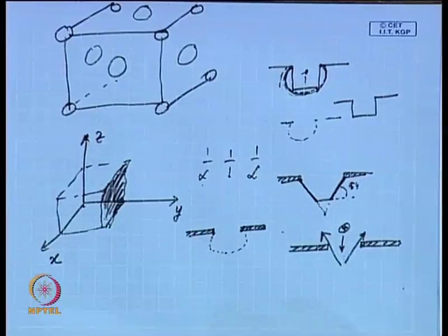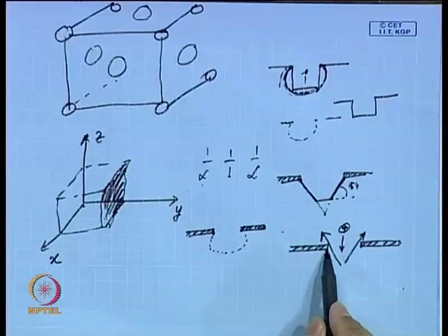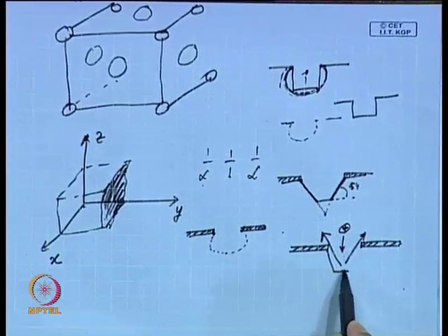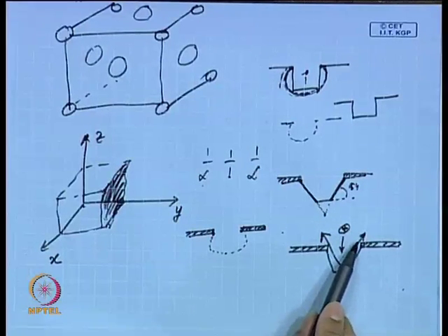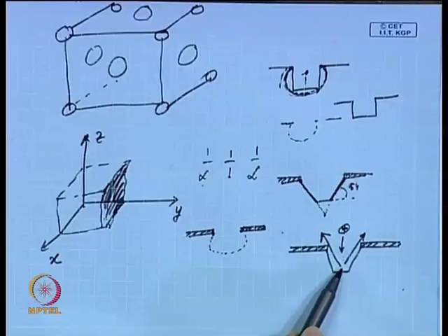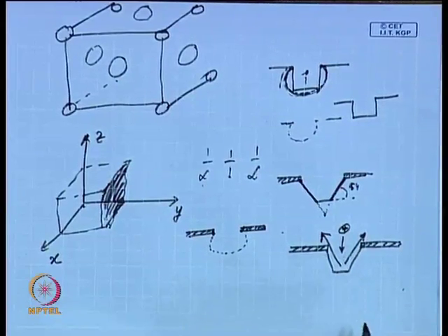So, automatically the plane that you cut forms a layer like this, because when the reflection takes place, that reflection will chip away the silicon material. So, automatically you develop an anisotropy, but mind it, this anisotropy is not caused by the crystalline structure. This anisotropy is caused by the system itself. You have chosen your system that way.